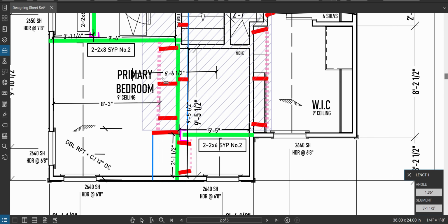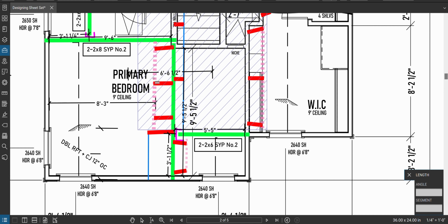This purlin is a support for the rafters, and the next support is over here on the wall. The rafter runs from the wall, supported by the purlin, and I'm basically responsible for all of the width across here. From halfway from purlin to wall is about there, and that's going to go halfway from ridge to purlin, which is about there.